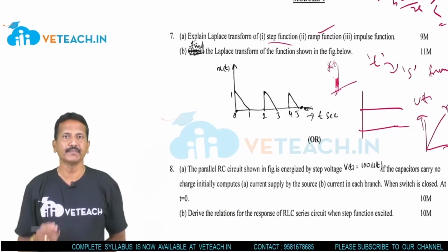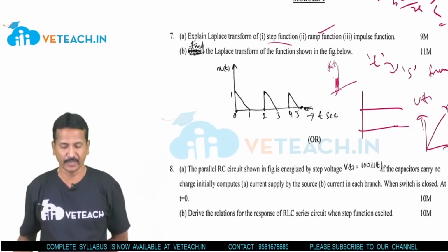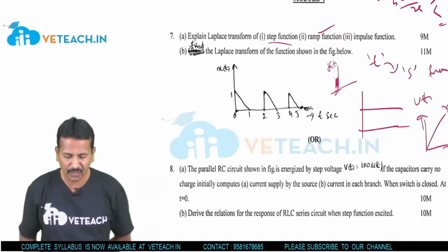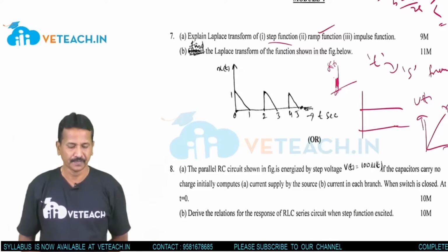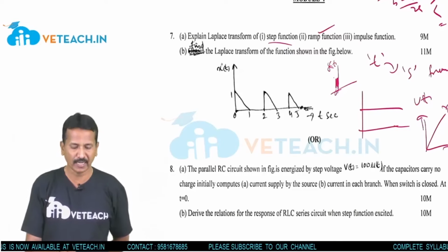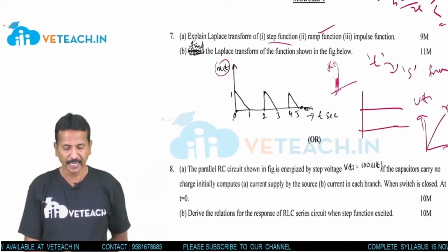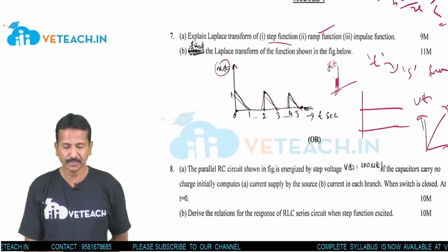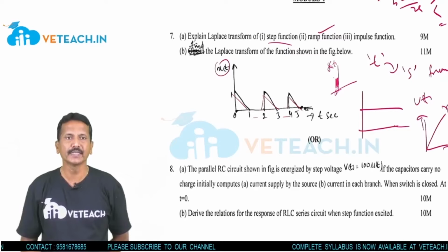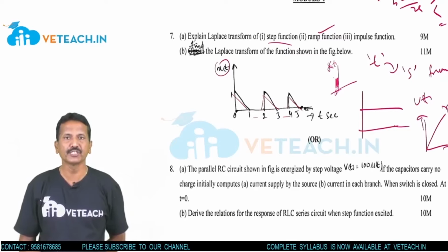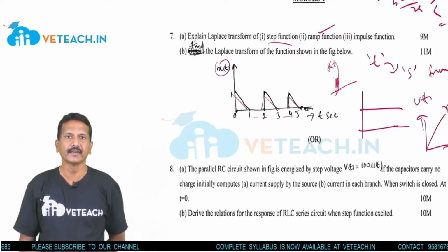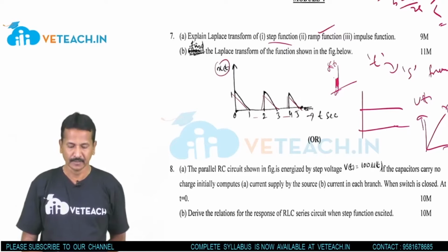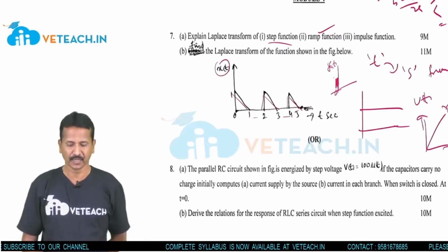So, time to the frequency domain. Find the Laplace transform of the function shown in the figure. A waveform is given here with respect to time t. Apply the Laplace transform of x of t to get x of s, and here the intervals are given. This is not continuous, it has some discontinuity. Applying the limits, first find the time constants, then apply the Laplace transform, then we can know the response of the system.